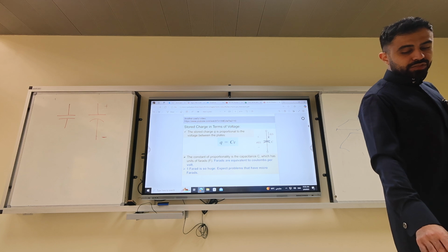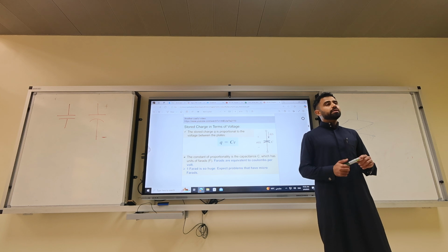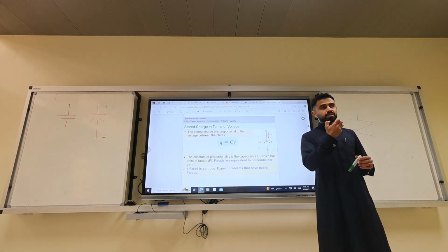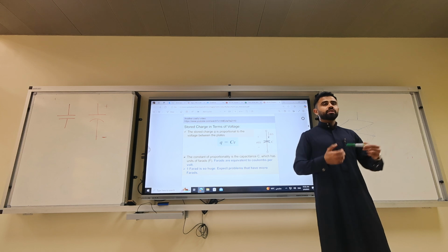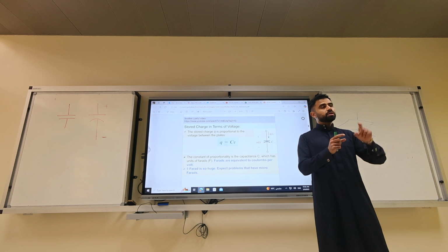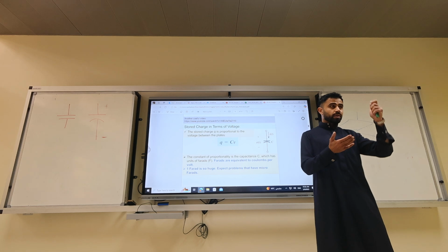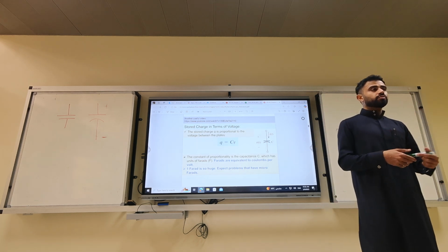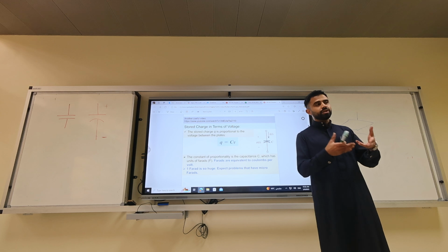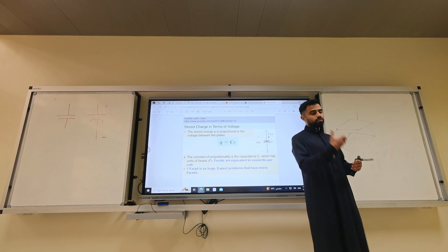Well, there are many applications for capacitors. One major application, if you are familiar with the radio: the radio devices, the ones that you use to communicate, use a capacitor and an inductor. If you change the variables, you can tune into a certain frequency. To tune the frequency, the product of the LC circuit has to match the frequency. That's why I told you it's AC. It's operated with AC. Its main benefits are with AC, and very few benefits if you connect it with DC.